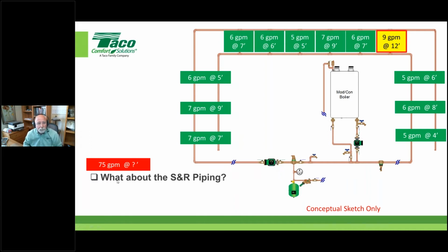But how do we come up with that number that's based on the total pressure drop that the circulator needs to overcome? What about all that extended header, right? What about the supplies and the returns coming back from all that? Regardless if it's 2-pipe direct, 2-pipe reverse, there's a bunch of pressure drop associated with that. Somebody's going to have to calculate that. And generally speaking, depending on how that person has designed their system, a lot of times the pressure drop through that header is significant, okay?